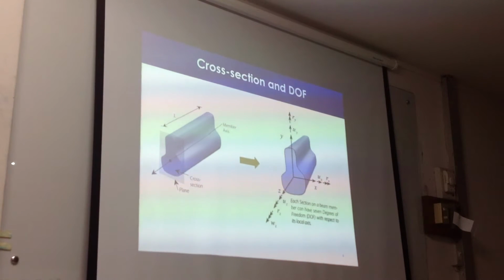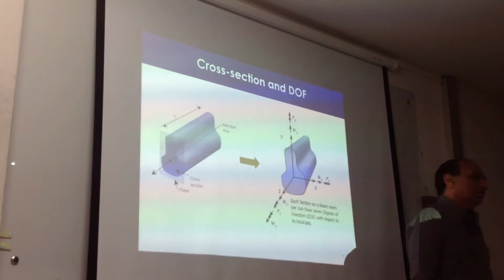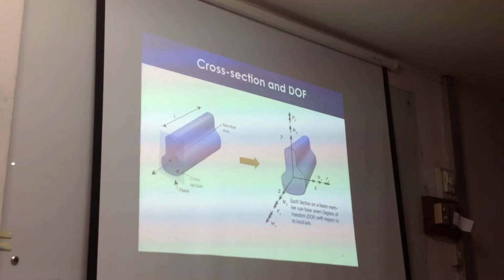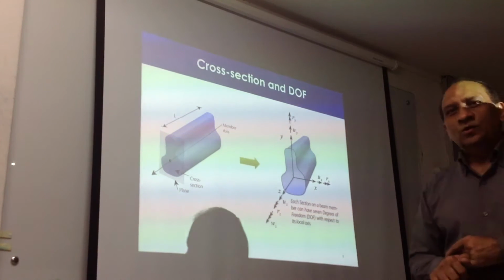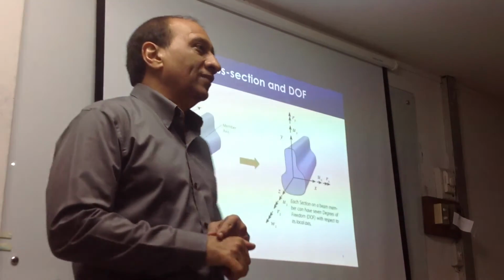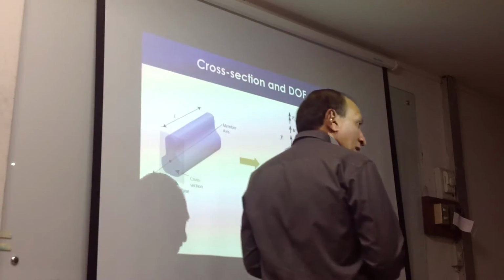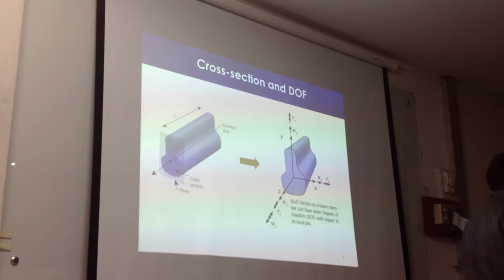Of course, you never heard about warping constant, so you do not know what it is. It is extremely difficult to calculate the warping constant of cross sections. There are very complicated equations to calculate it. Even the torsional constant J cannot be calculated reliably. In fact, if you had taken Professor Warsak's course in finite element, his first problem would be to write a finite element program to calculate the torsional constant of the beam, because the problem is so complex that you need finite element analysis. So for a general cross section, it is very hard to calculate these properties.